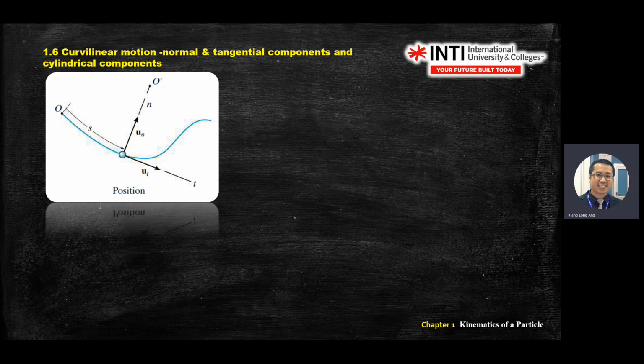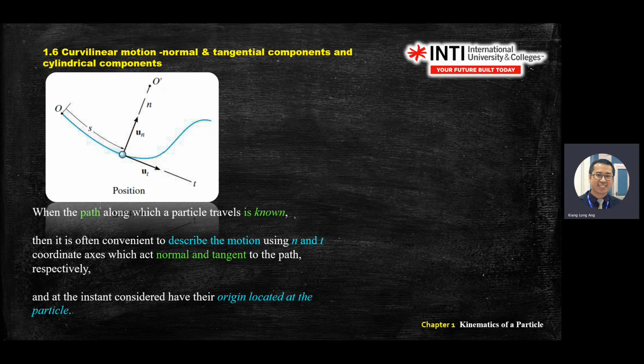If it's a Cartesian plane xy, but if your curvature, every time you see a curve question, you straight away use tangent and normal. Don't confuse yourself with x and y. Every time you see a curve, straight away go into normal tangent solution. Okay, so you have ut, un pointing inside, and the origin O prime means the curve center. Okay, the rest you read, nothing complex here.